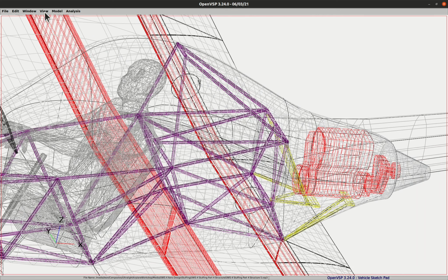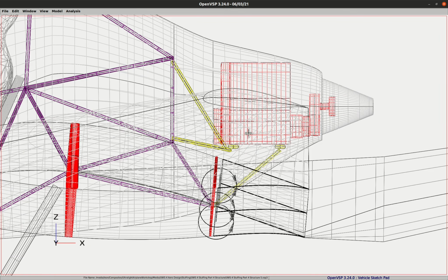So let's take a look at the left side again. I'm thinking of the motor mount transferring load up to this point and to this point, and then also transferring load down to this point. Now this bar here, its sole purpose is to keep rocking from this direction from being an issue. It's going to take this rocking load and transfer it down here and of course here. It does not handle any torsional load due to slowing down or speeding up of the engine. That's all handled back here.